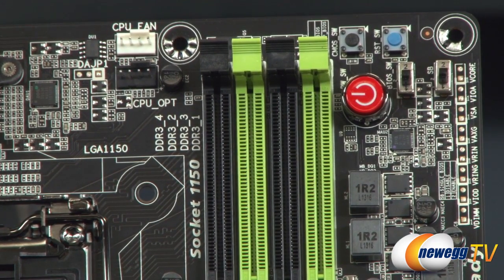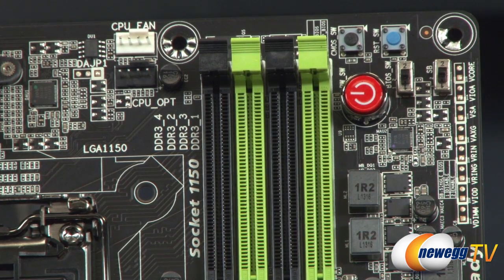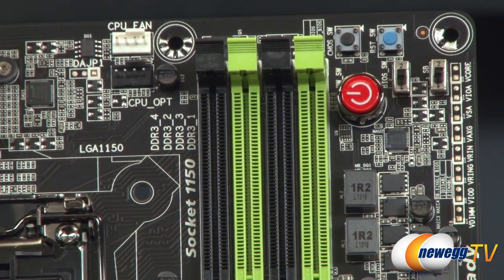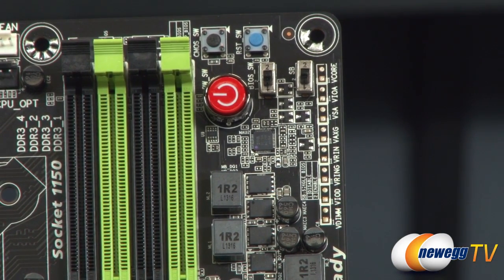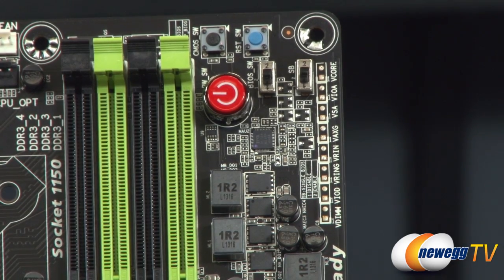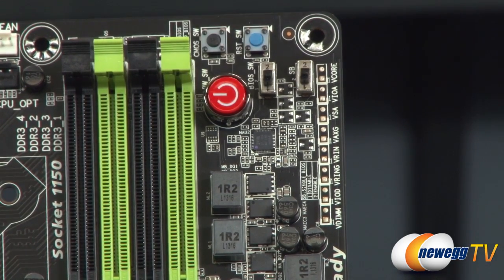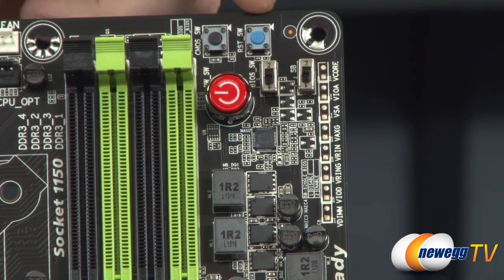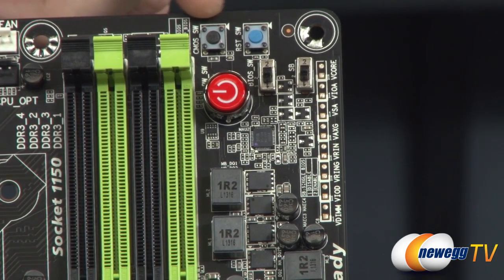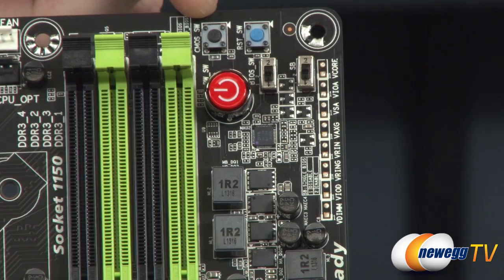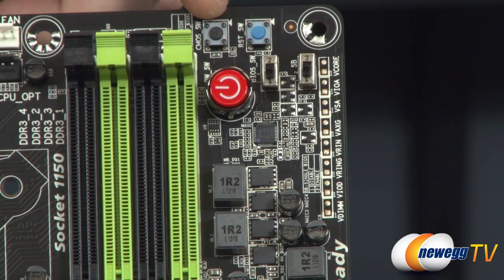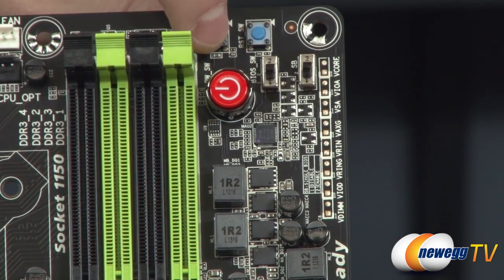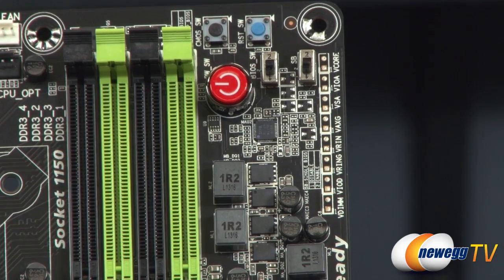That's very helpful because a lot of times when you're building a new system, you'll assemble it outside of the case and test out your parts before you do all that installation, because if you happen to have something defective, it's helpful to identify that right off the bat. Having that button allows you to turn the system on and off without having it wired up to your front panel connectors on your case. There's also a reset button right there, which simply does the reset function. And we mentioned that rear-mounted clear CMOS button on the Sabertooth board from Asus, and Gigabyte has put a clear CMOS button on the motherboard right there that you can push to clear the CMOS.